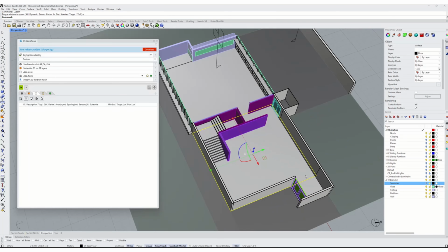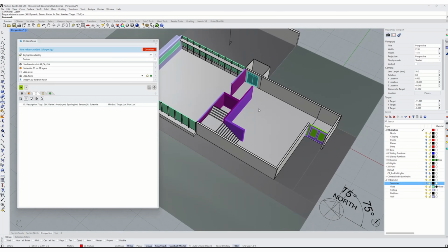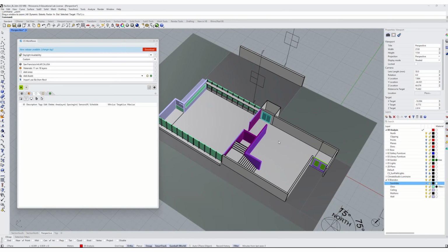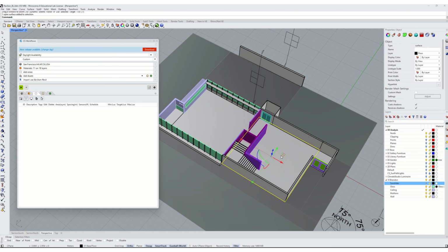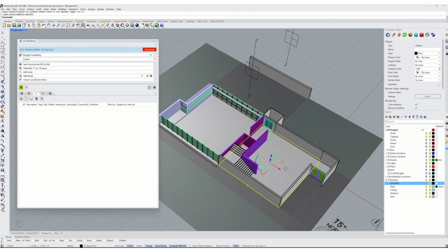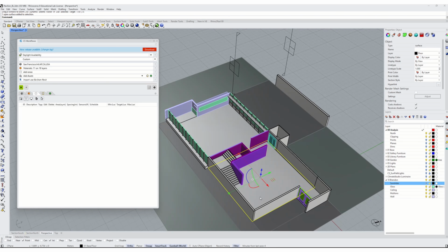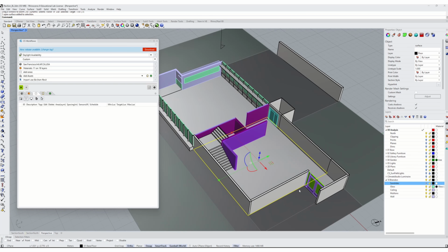The analysis zones we're going to select are going to be each of the individual floor plates inside the galleries and the reading room. And so I'm actually not interested in the ones that won't get any daylight whatsoever, like the elevator lobby here or underneath the stairs. So I'm going to have to trim this floor material in order to come up with a useful analysis zone.